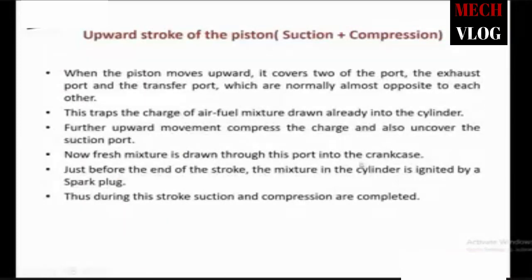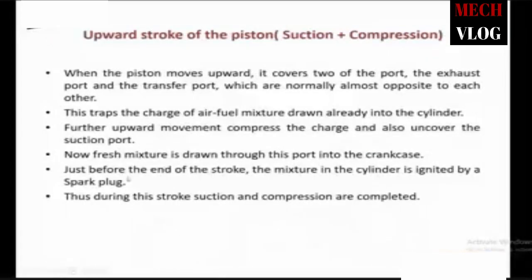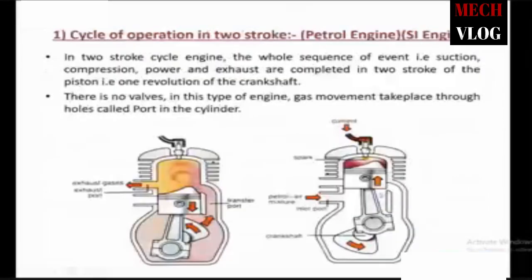Further upward, now the fresh mixture is drawn through the ports into the crankcase. Due to the pressure difference, the petrol air mixture enters the crankcase. And just before the end of the stroke, the mixture in the cylinder is ignited by a spark plug. Thus, during this stroke, suction and compression are completed. So at the end of the compression stroke, the spark plug ignites and the power stroke begins. That will happen up to this section.